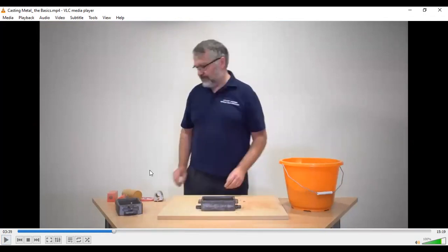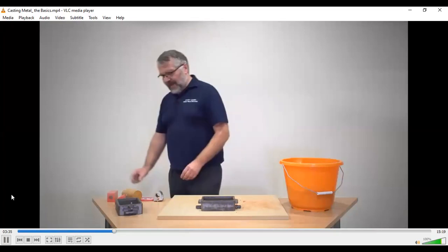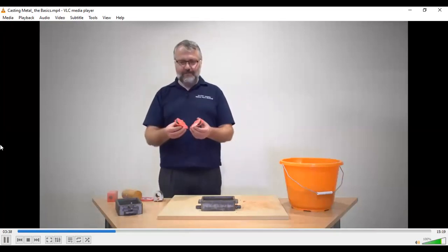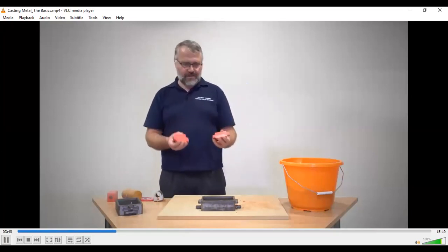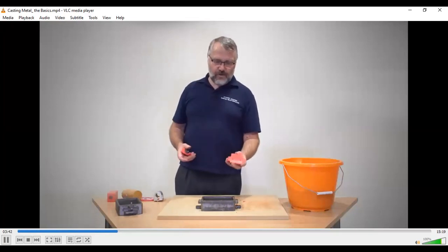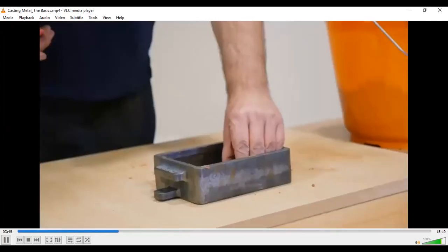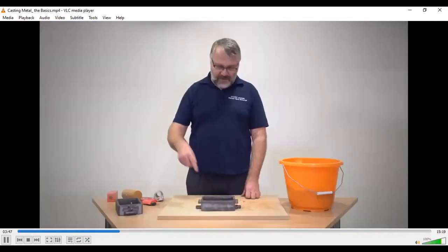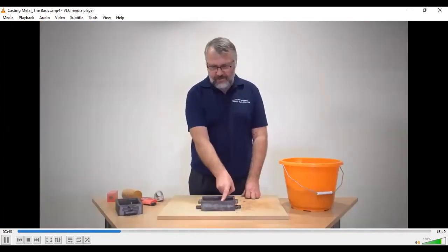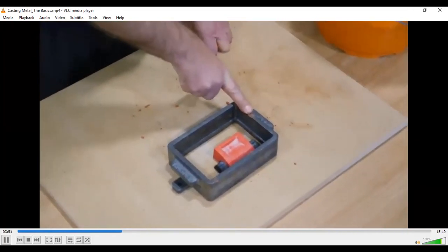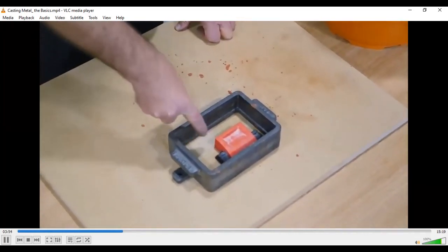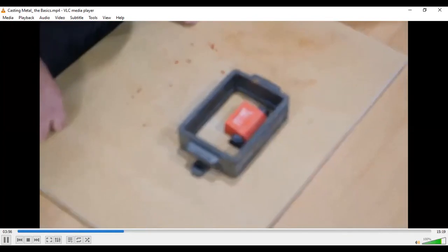Now carefully see, that is the basic steps that you have to perform, right? Using that drag, and then he'll place the pattern. Observe carefully. And add the first part of the pattern. One side has locating pins, so it sits flat. We'll use the side with the holes face down in the moulding box. This has been set so that nothing touches the sides of the moulding box, and there's a space in the corner for us to complete the moulding work.